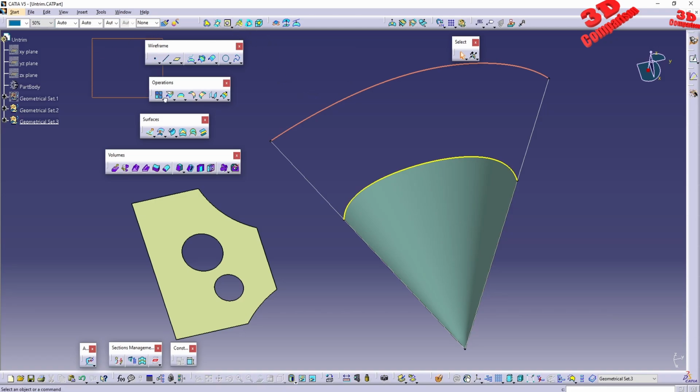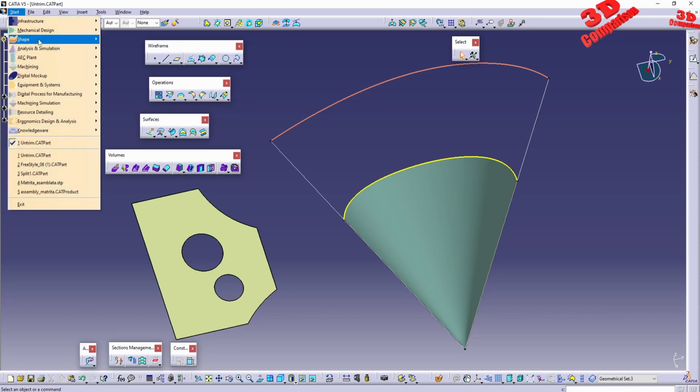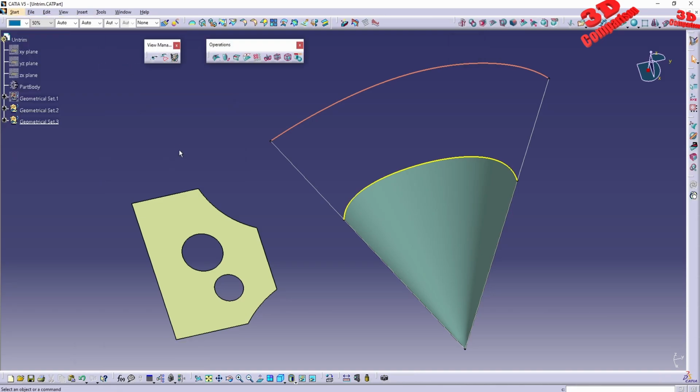Now, these are the main features for CATIA surface modeling, but keep in mind that this is generative shape design. If I swap the workbench and go to something like Imagine and Shape, we're going to see a lot of features over here as well. Some of them, as you see, are present within generative shape design, for example, boundary and extract and multiple extract. These were also present over there, and they will share the same functionality and same icon, and they will work over here as well.